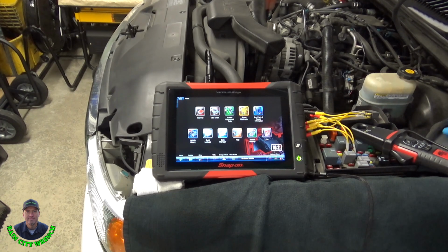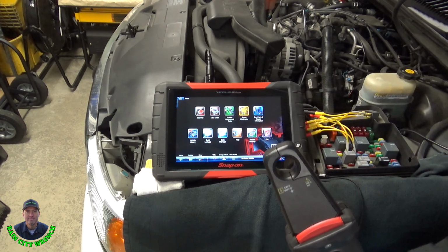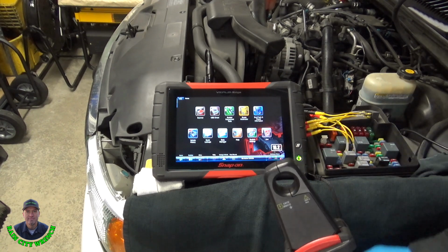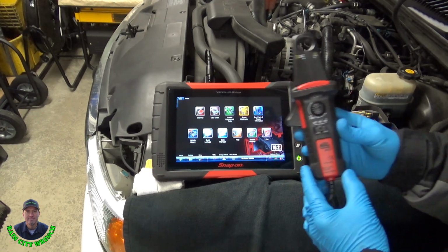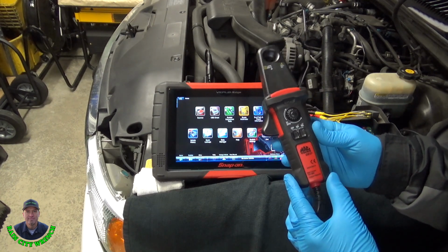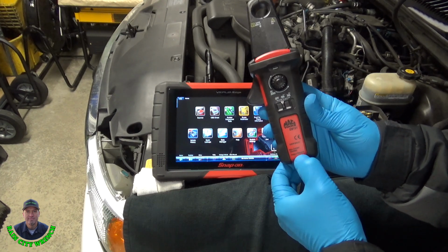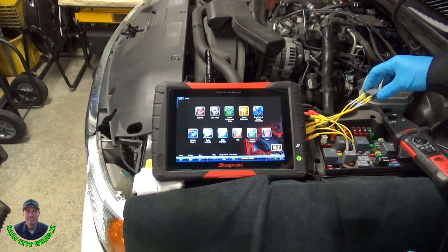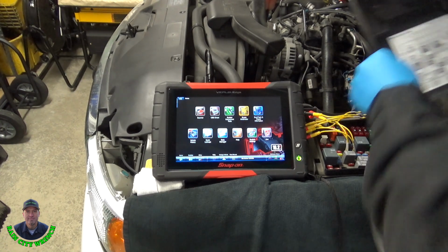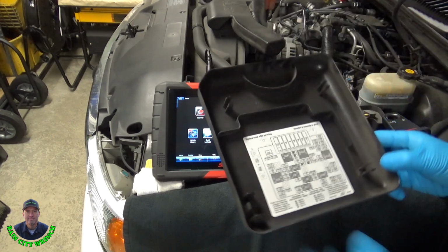The next test I'm going to do is to look at this fuel pump pattern. I've never looked at the fuel pump pattern on my own rig. I'm going to use this Mac Tools EM121 low current clamp, and this is 100 millivolts per amp. I already had the fuel pump relay out, so I just jumpered in using the leads out of my AES set.